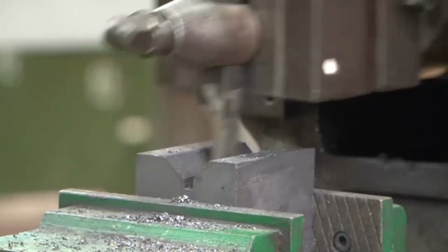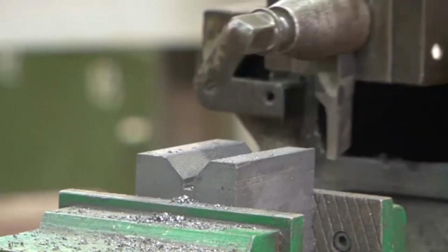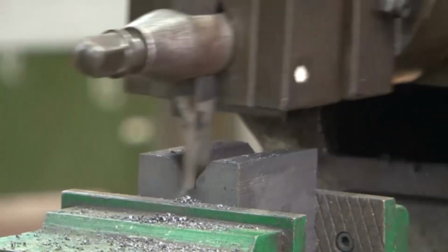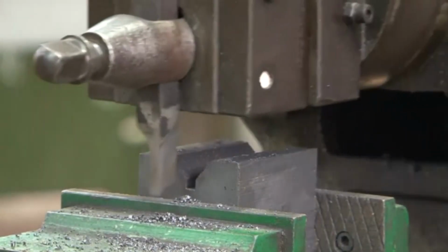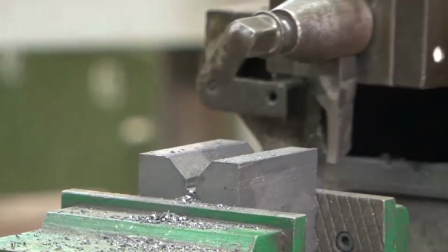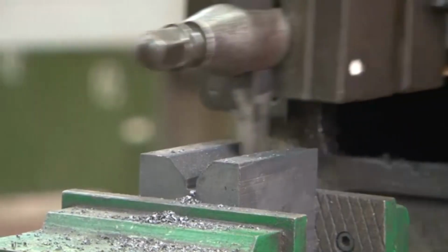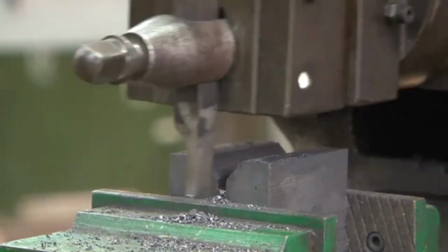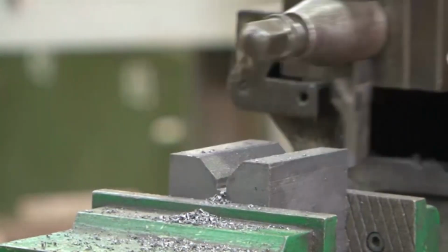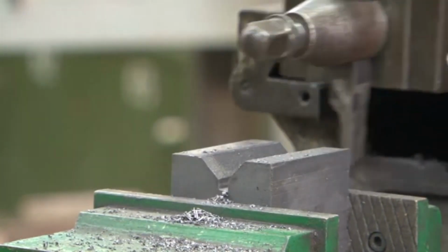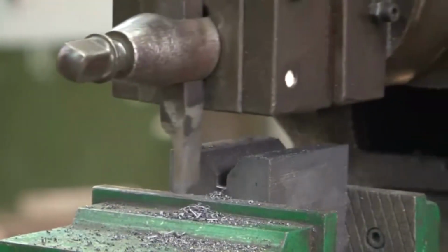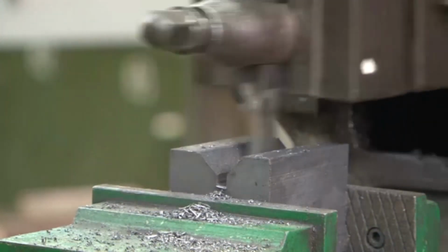and once again, during the forward motion the material is being removed, and during the return motion the material is not being removed, therefore the return stroke or the return motion is at a higher speed than the forward motion. Here the workpiece is not given any feed, as you understand, because we do not want any wider groove than the width of the tool.